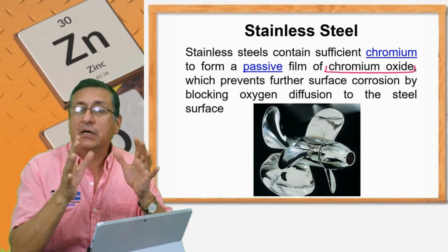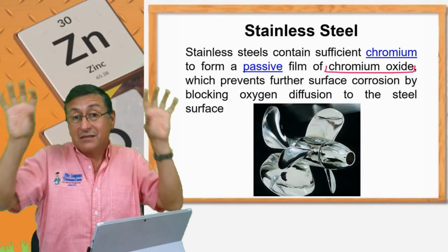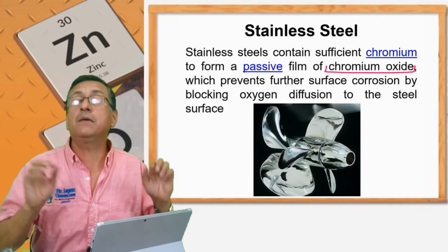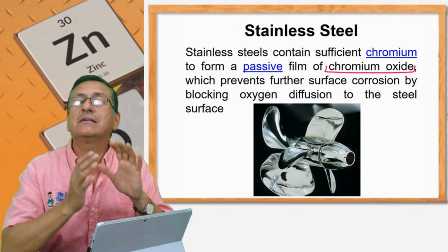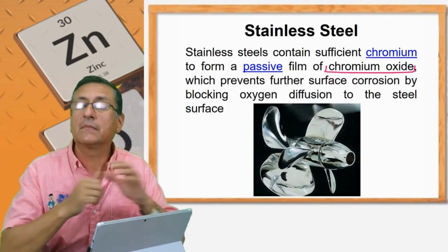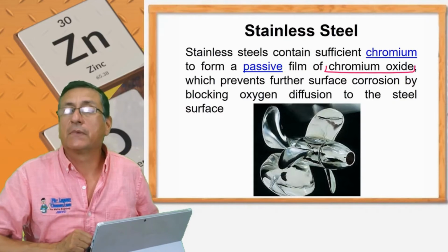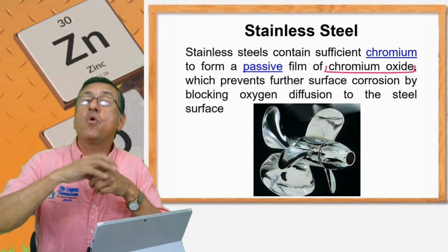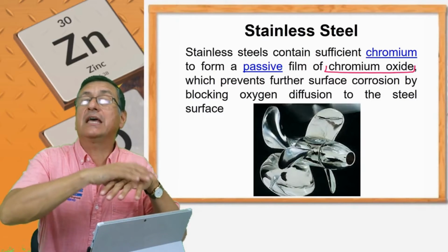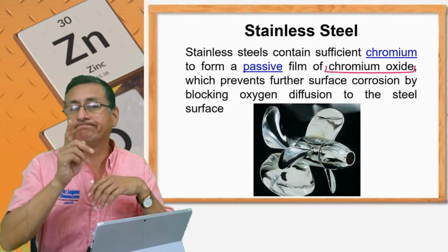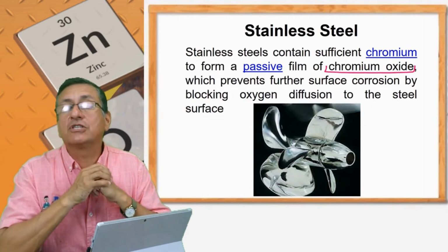For that reason, a good tip to keep the stainless steel protected from corrosion is to keep the stainless steel clean and polished. If the stainless steel is clean, the stainless steel is protected by itself. Right? The enemy is when water, stagnant water or a wet surface, stays over there for a long period of time and destroys that film of oxide of chromium.